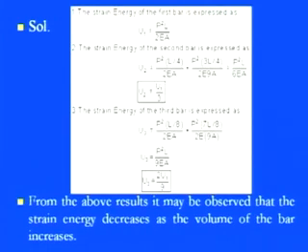So the total strain energy for the first bar is pretty simple, because we have straight relations. So U1 is P squared L by 2EA. As I told you, this strain energy absolutely depends on the load application, P squared, and on E into A. So this is very straightforward. Simply by putting in the values, you can get the strain energy of that bar.